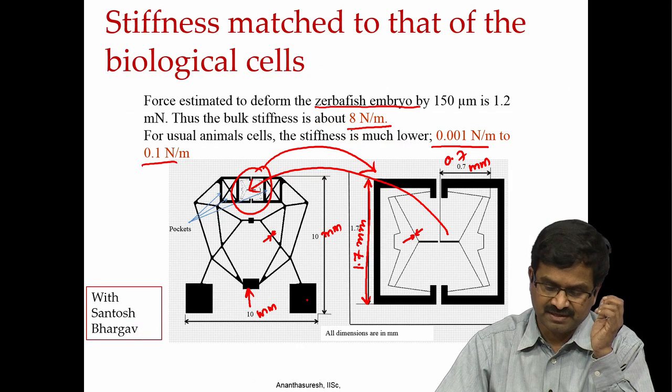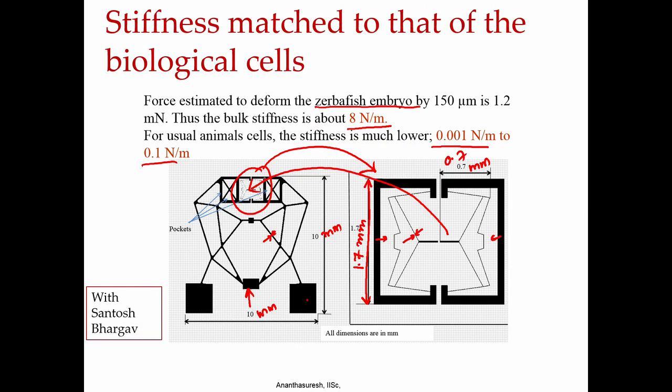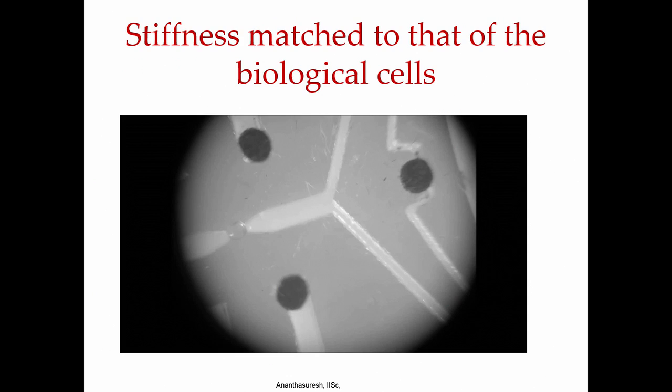Big one, what it does here is when we apply the force, it will bring this portion and this portion, which you see here and here, closer. Once they go there, here is where our contact is happening again, they touch, it is also a CCM. When they touch, then the force starts, this one starts going this way, this one will start going this way, they will grab the cell. Okay. And likewise there is a DACM here which will amplify the displacement there. So, you can measure the displacement and compute the forces. So, a lot of things in one mechanism.